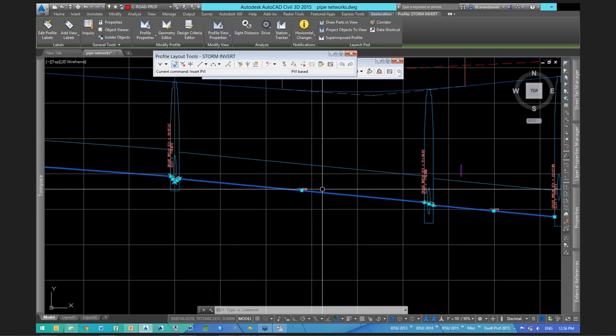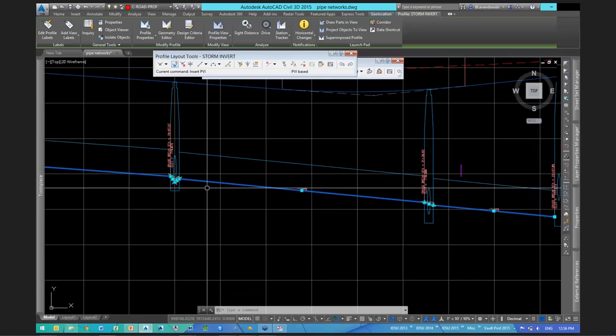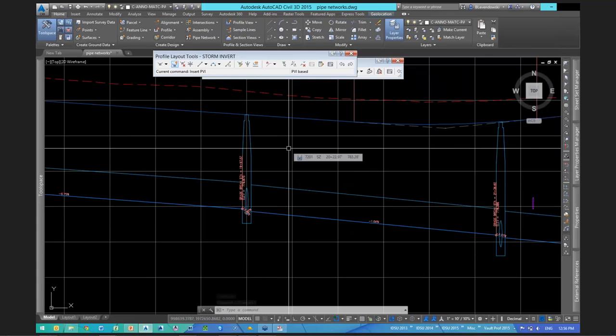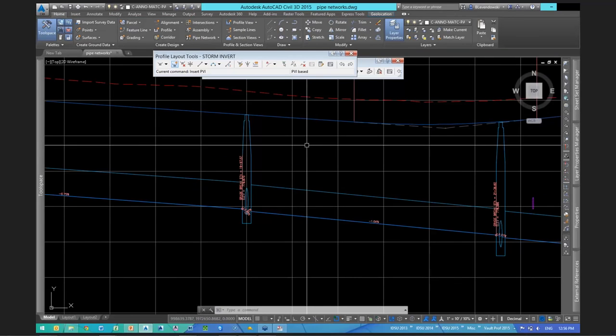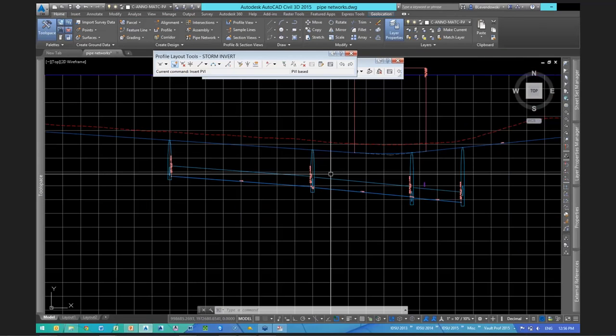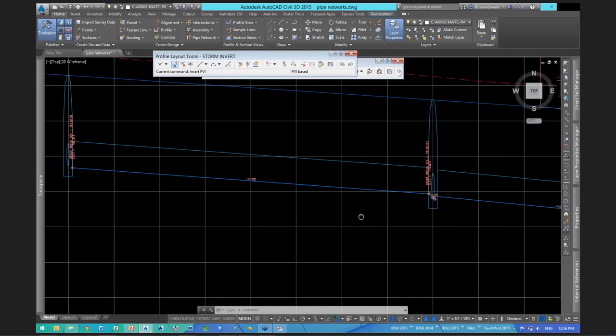So I can export this to XML. With the Trimble Link add-on, for example, I can export to an RXL file. That'll take an alignment and a profile, and it's fairly foolproof for the surveyor staking this.